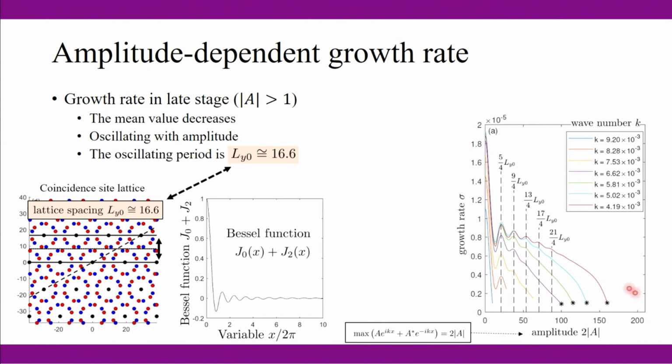And for the simulation, the endpoint here is where the dislocation emission occurs, because the amplitude becomes so large. So in the end, you have this dislocation nucleating at the trough and you start to see this dislocation emission.